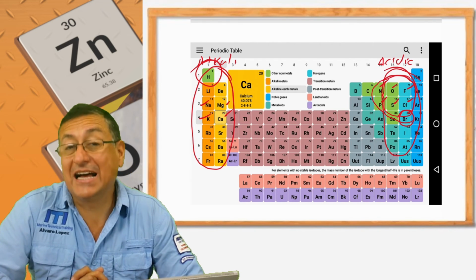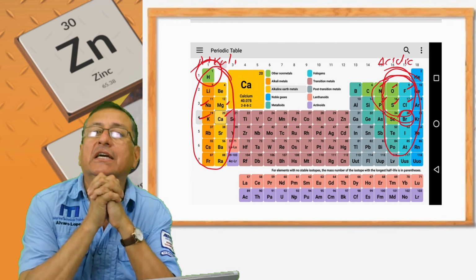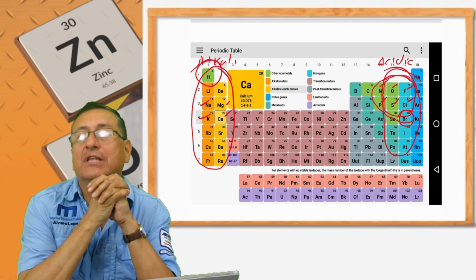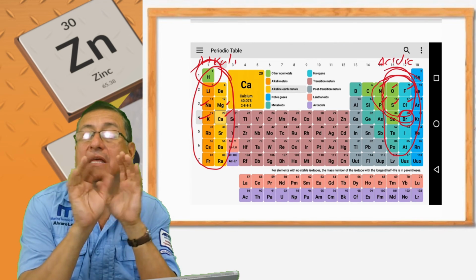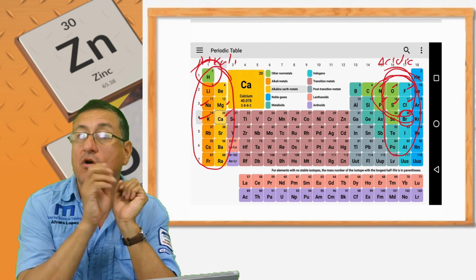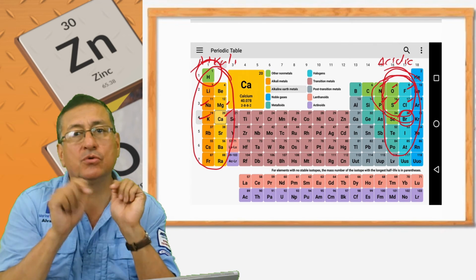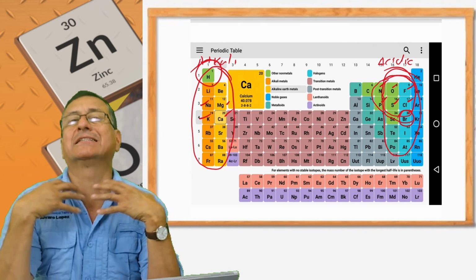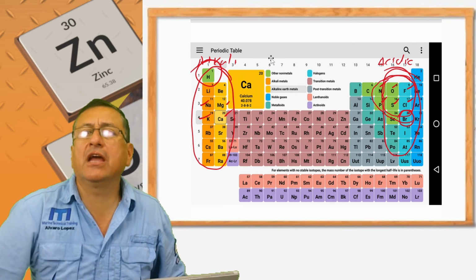And those acids attack. For that reason, when you have free hydrogen in the environment, that free hydrogen combined with the chlorine of the salt water produces acid, and those acids attack the metals and accelerate the corrosion. Simple. How can I get free hydrogen?